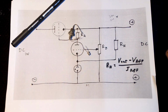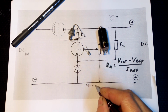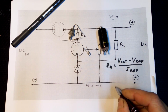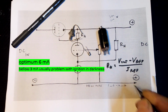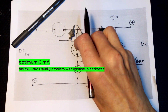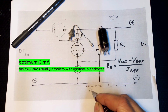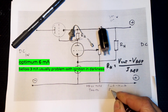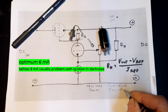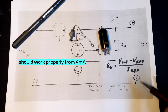For example, for a neon tube, the current is usually somewhere between 1 milliamp and 10 milliamps. For this IC, TAA550, it is usually between 5 milliamps and 15 milliamps. And we have to remember that with 15 milliamps we have to dissipate this power somewhere.